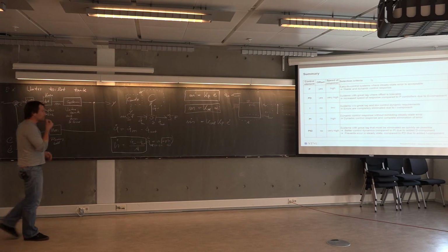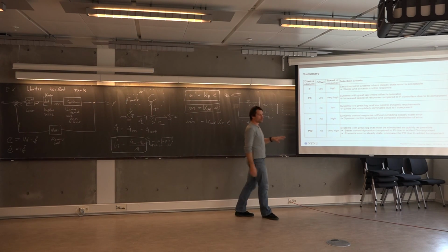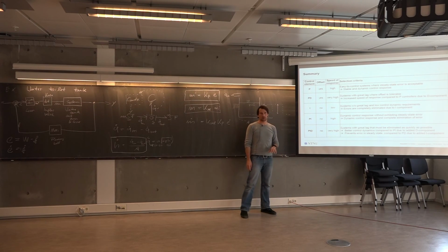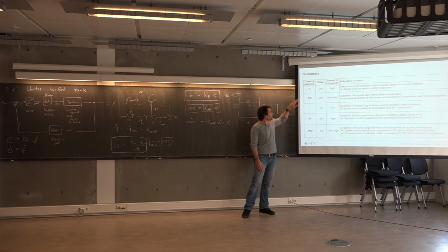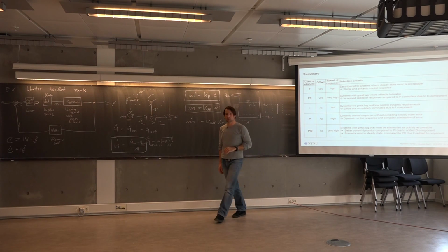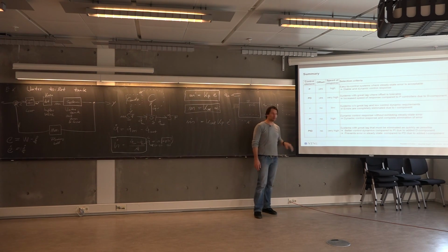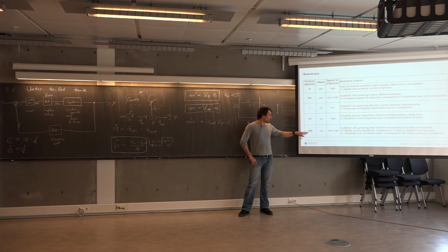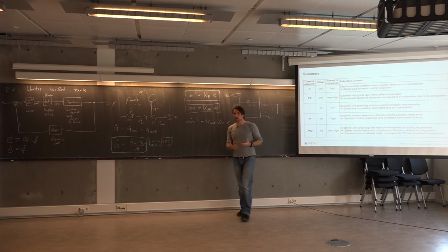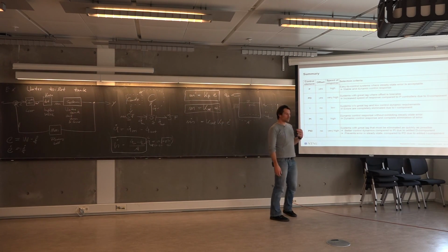Okay, so just to sum this up briefly, different types of controllers that you may use in order to control such a technical system. P and I can be used as standalone controllers, but in general, especially these days, a PID controller, I guess, is the standard workhorse in most applications. And the benefit of this one is that it basically combines all the benefits of the individual controllers, meaning that it has a very fast response.